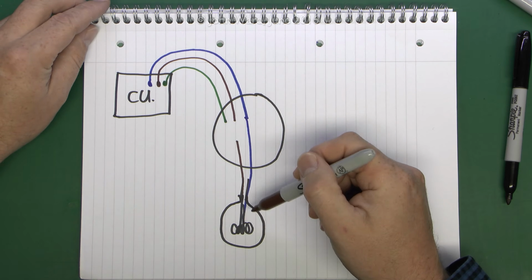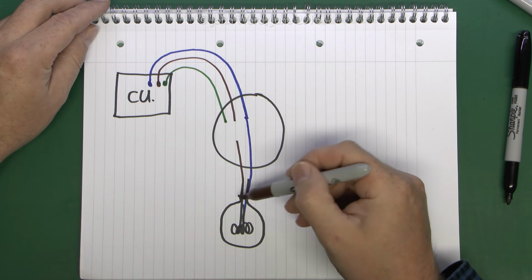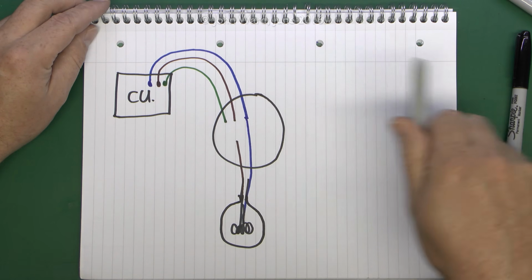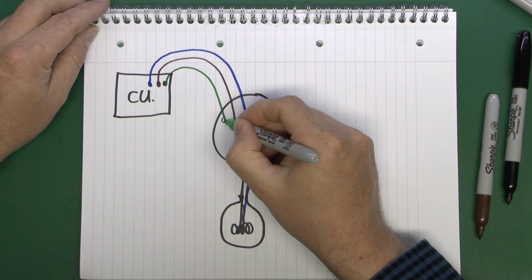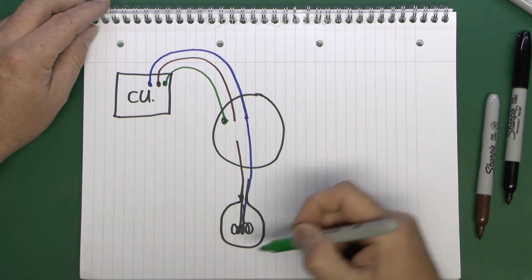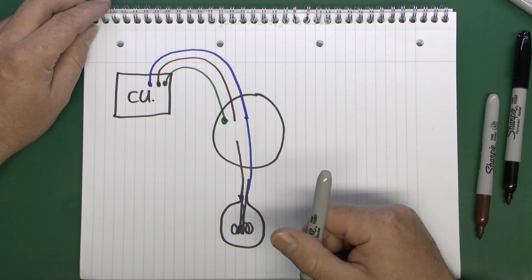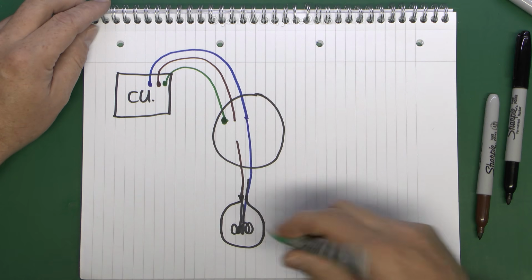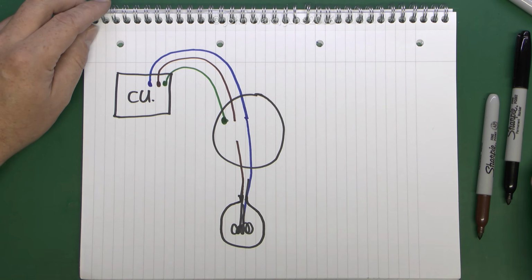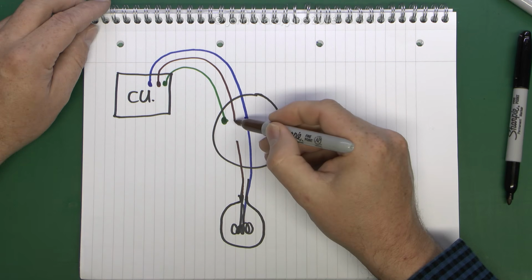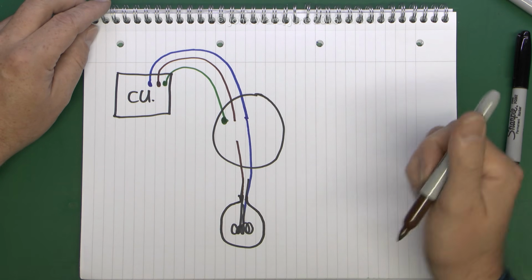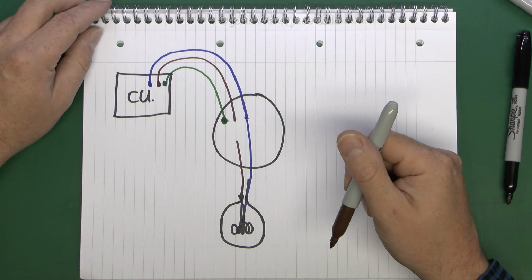Now, light holders in the UK are typically made of plastic, and this is just a 2-core flex. So although the earth connection is here in the light fitting, generally it's not actually connected to the lamp holder itself, unless it was made of metal or be a fairly unusual type, but earth is always taken to the actual rose itself. Now, if we connected these two together, then the light would be on 100% of the time, and there'd be no way of controlling it.